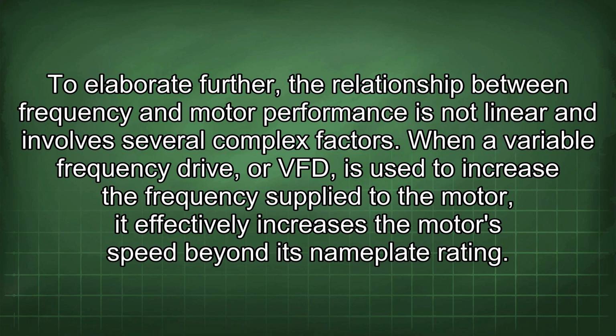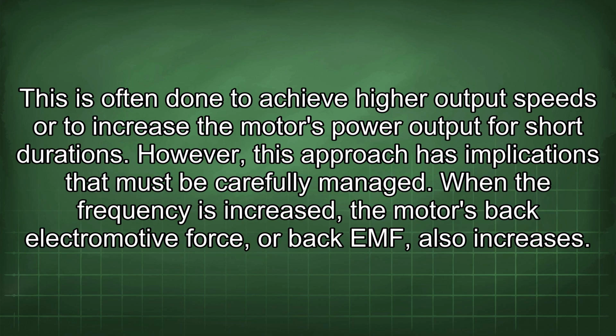To elaborate further, the relationship between frequency and motor performance is not linear and involves several complex factors. When a variable frequency drive, or VFD, is used to increase the frequency supplied to the motor, it effectively increases the motor's speed beyond its nameplate rating. This is often done to achieve higher output speed or to increase the motor's power output for short durations. However, this approach has implications that must be carefully managed.